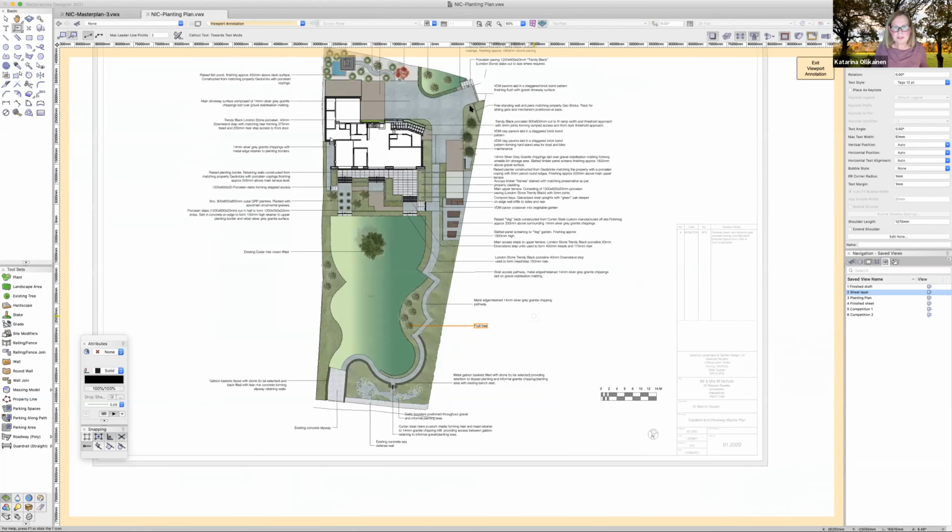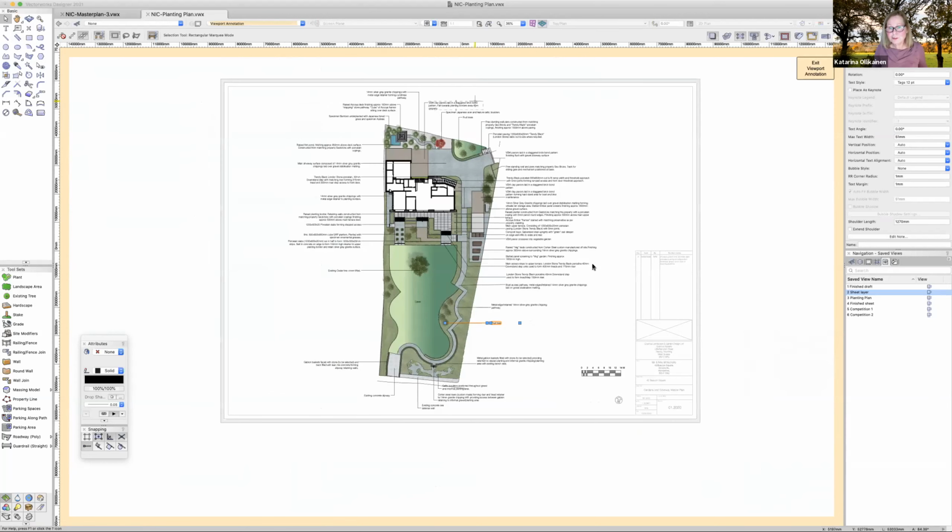This way, if you put the annotations in the viewport, first of all, you know you have the right size, so that if you need to shrink the design to fit onto a paper, your text is not going to shrink at the same time. You know you will have readable text as an end result. And also you don't have all these annotations messing up your design layers and being in the way. You have to turn off classes here and there and so on. Everything is gathered on your sheet layer and you can easily amend it when the changes are coming.